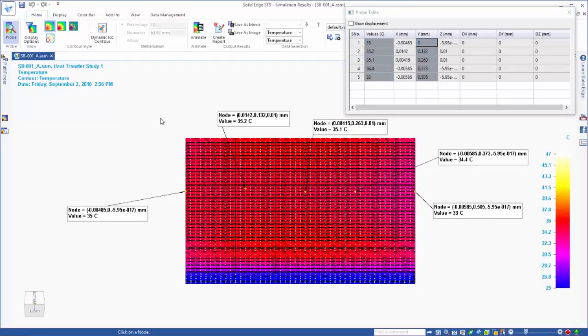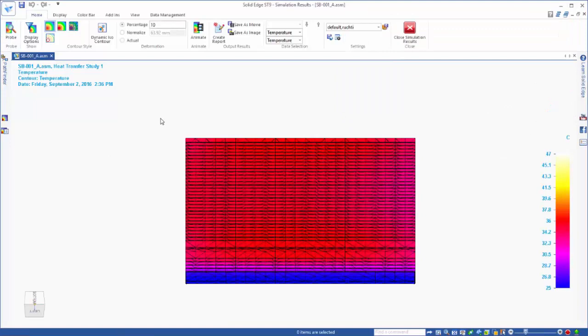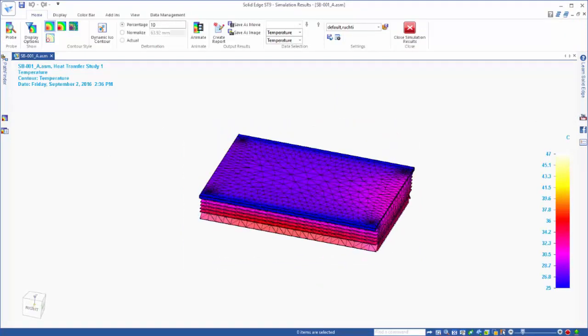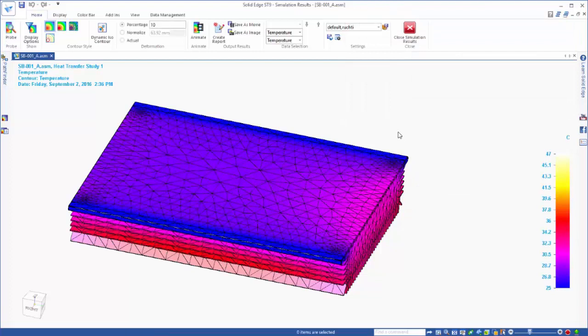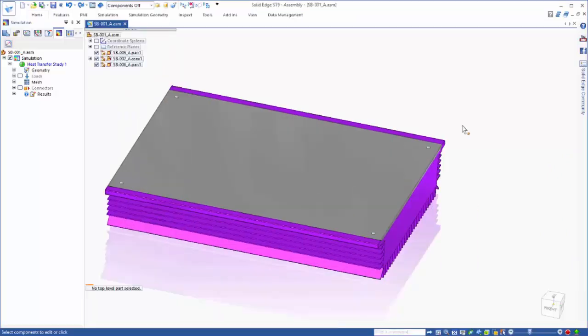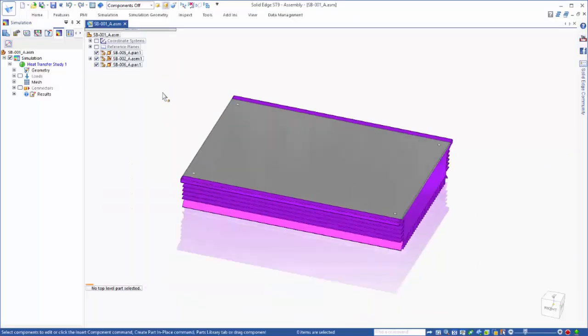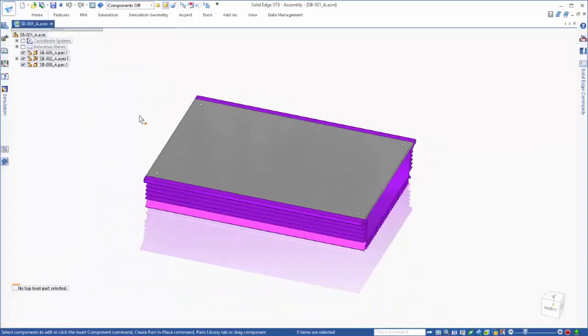In addition to the temperatures along the casing, we also need to probe the lid to see the maximum temperature reached while in use. Another quick probe and we can see a maximum temperature of 31.1. The reason for finding the maximum temperature is so we know how the lid will react once heat is applied to it. This reaction is called thermal expansion. Thermal expansion is the swelling or enlarging of a material as heat is applied. This can lead to problems as stress gets placed on the mounting holes where the lid is held in place.